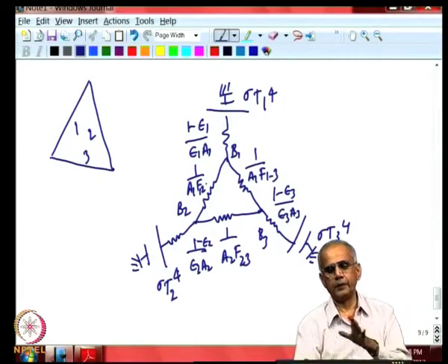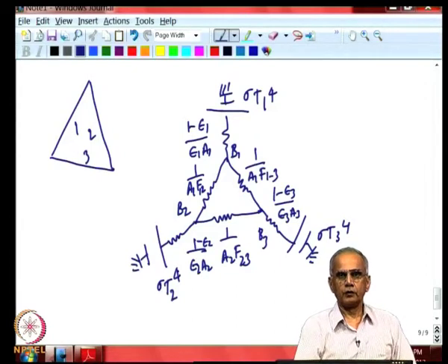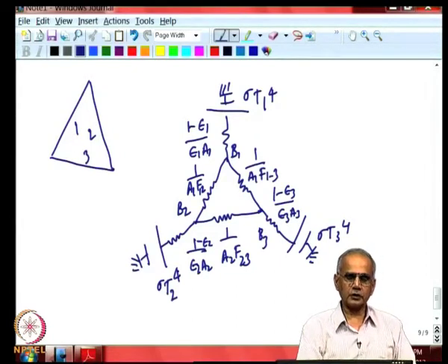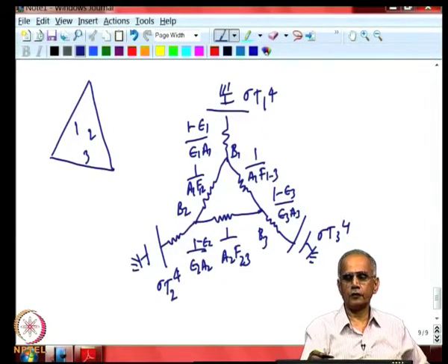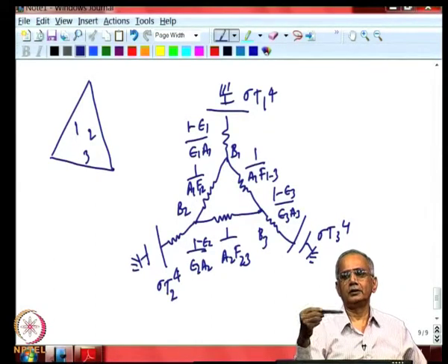So, we have the complete resistance diagram now for an enclosure consisting of 3 gray diffuse isotropic surfaces, and they consist of 3 potentials here, and then we have 3 surface resistance terms, because the surface is not a black body, and 3 geometric resistance terms on account of the relative configuration of the 3 surfaces.